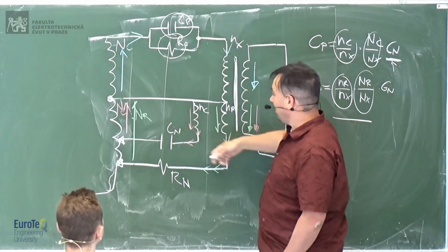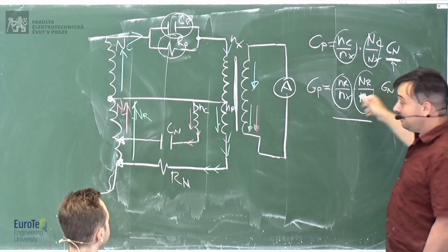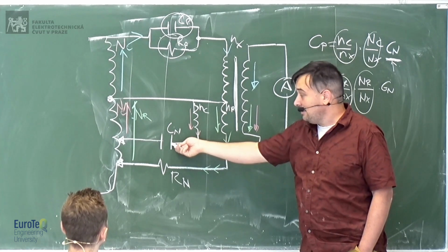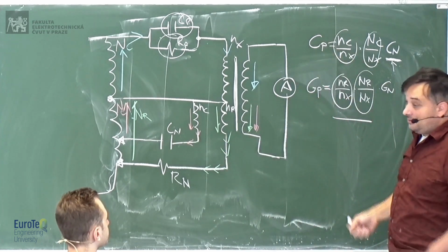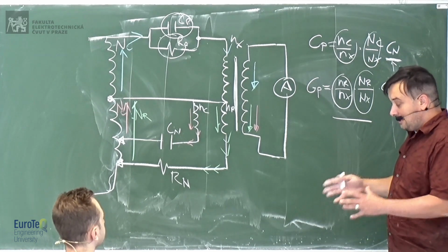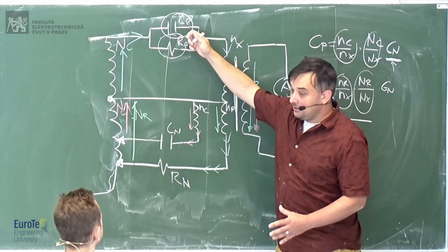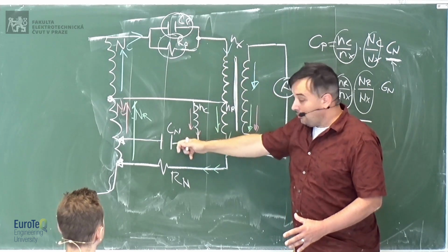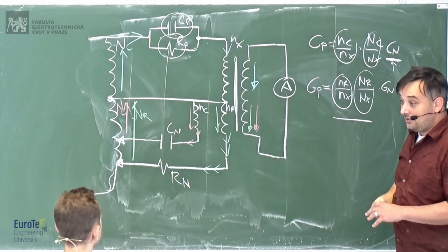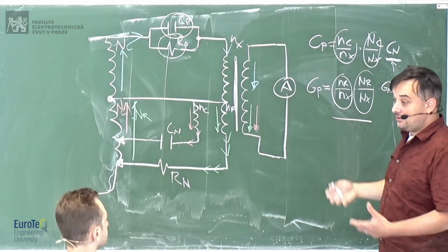Of the same amplitude, more or less, you will have the same number of turns here. So you can actually measure this capacitance and have almost the same uncertainty as your reference, which is good because you have a very good standard with very low uncertainty. And you can calibrate this capacitance almost having only this as a source of uncertainty, which is very good, okay? So this is a method if you don't want to add additional sources of uncertainty to your system.